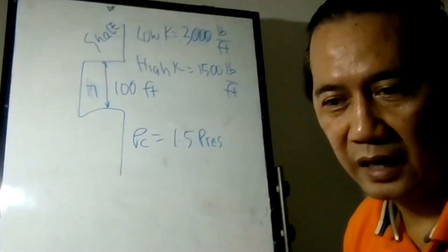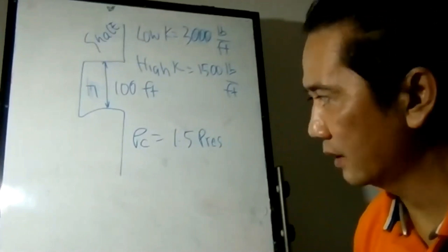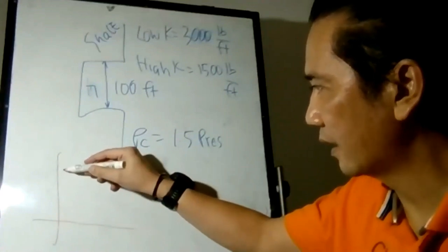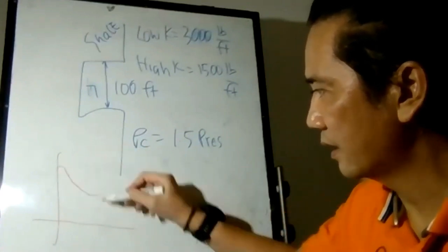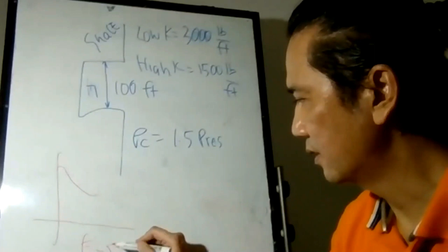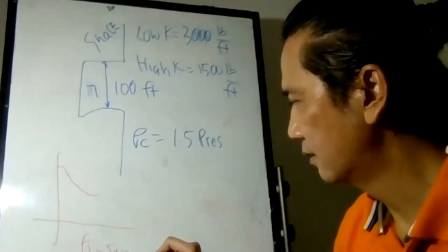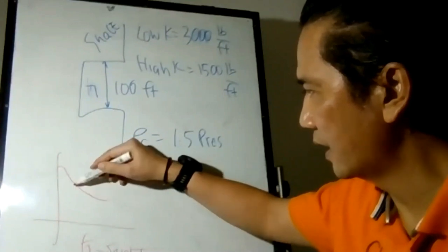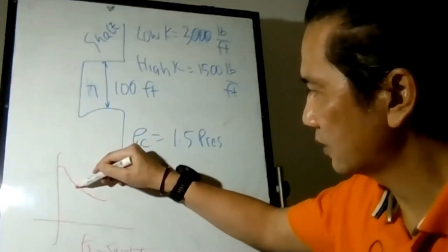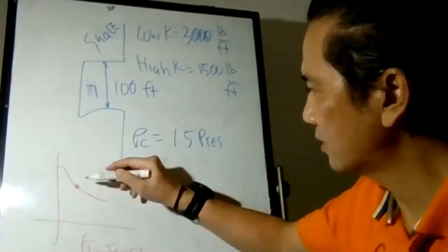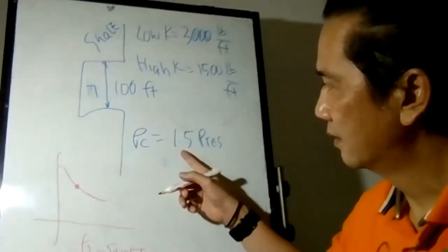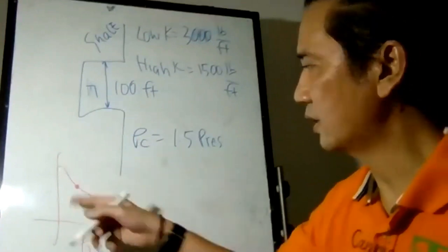You pump with a high rate, with the frac fluid and everything. Then from the decline analysis, there is a G function here. This is what we call the G function. Then you decide which one is the actual closure pressure. So let's say the actual closure pressure is here, then you have to modify your design, which was previously assumed, with that one.